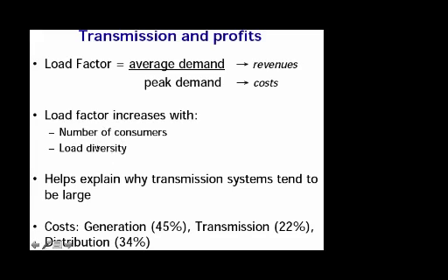Because imagine that, even for my small electrical needs, I need 2,000 watts at one point, for instance, when I run my microwave oven. That would mean I need to have 2,000 watts of capacity if it were just for me, even though I use on average 100 watts. However, if we lump in 35 million people, it's very unlikely that all these different people are going to start their microwave ovens at the same time. That will increase your load factor.